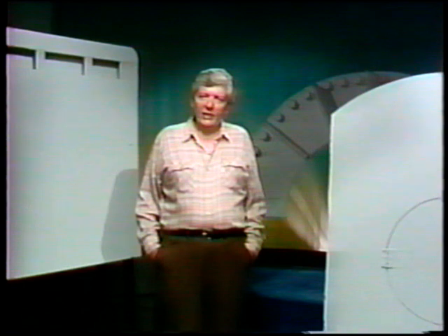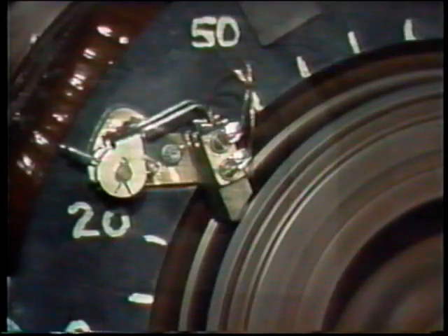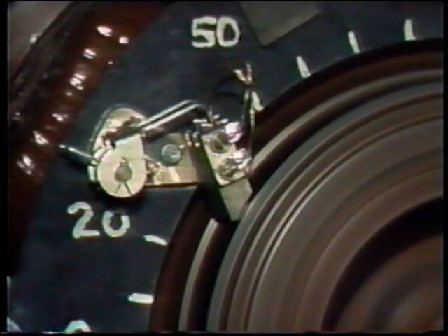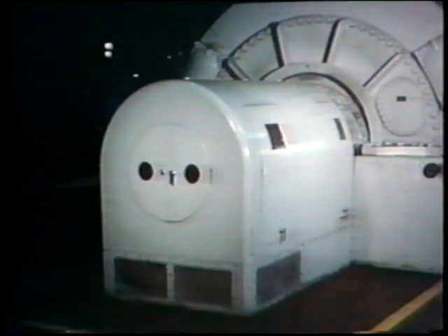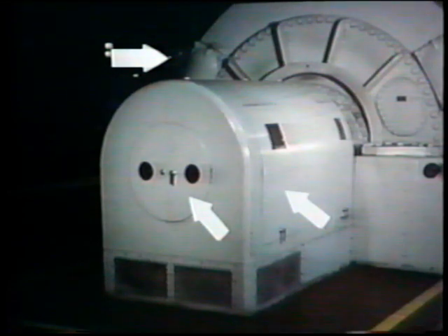To operate, it must have a separate source of DC power. This comes from another DC generator called a pilot exciter. The pilot exciter is a small, self-excited DC generator, and its output is collected by a third set of brushes. The pilot exciter supplies excitation for the main exciter. So we've actually got three generators here: the pilot exciter, the main exciter, and the AC generator. All three are driven by the same shaft.